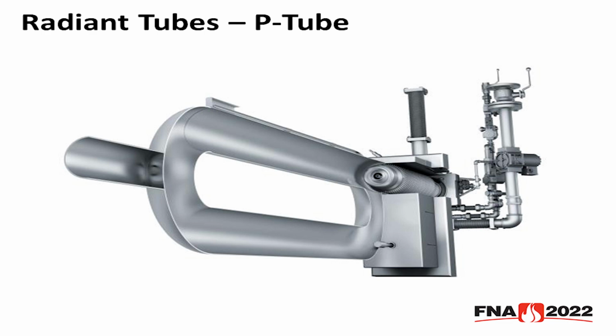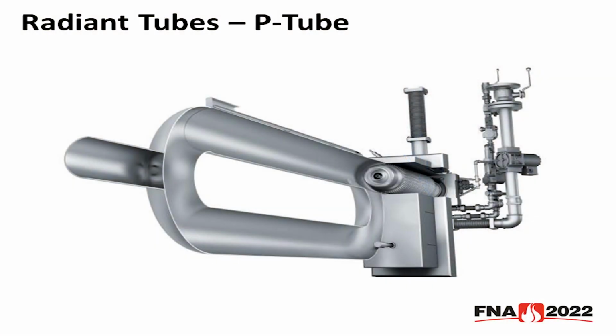This one's equipped with a self-recuperative burner. As I said, high velocity flame, pulse fired, individual valve control on each burner. So unlike a proportionally controlled system, if one burner goes out, it doesn't affect any of the others in the zone. So this burner fires into the upper leg, exhaust products travel back through the return leg, up through the cross connection, and then the high velocity jet creates a Venturi effect to re-entrain a portion of the exhaust gases back into the upper leg.